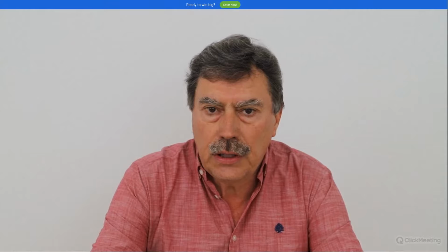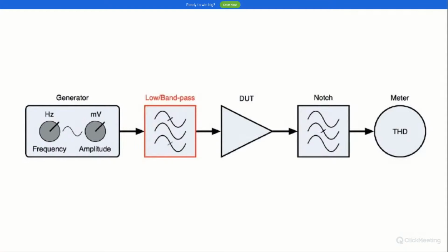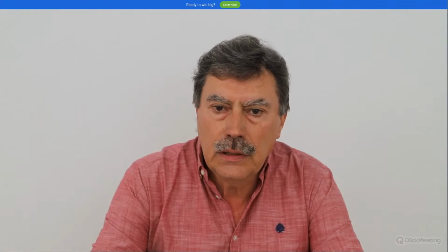Second, we insert a notch into the chain like shown in the next picture. The signal will be attenuated to a level where the digitizer and its amps do not add harmonics. Of course, the low or bandpass filter, the test frequency and the notch need to match together. Since the level at the output of the notch is typically small, we can amplify it in the notch or at the input control of the digitizer. The levels of the measured harmonics need to be corrected by the value of the gain.